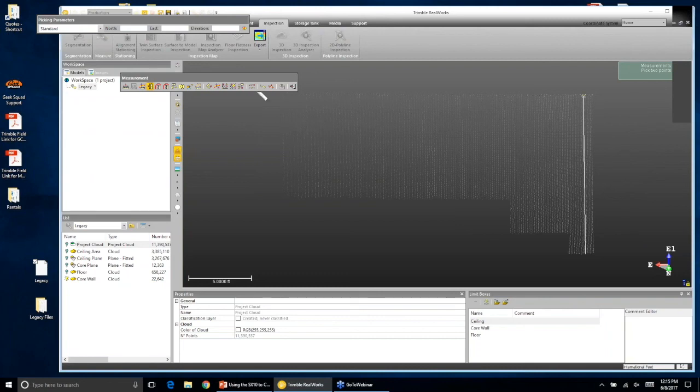I haven't shown you this yet, but along with the measurement tool, if I grab on a point, it will give me the coordinate for that point. So here we're 9 feet in elevation above what the machine called 0, and here is my real world coordinate for that exact point on the wall. So if I want to export out some points, I can select them, get those measurements, create a list, use that.